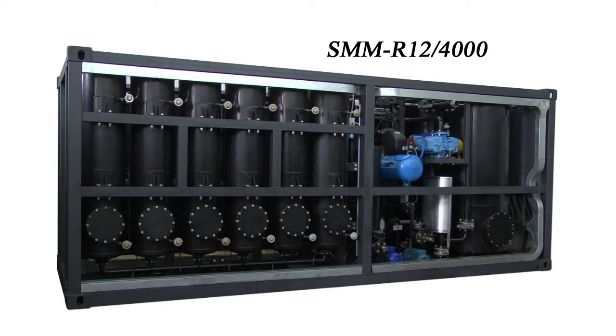When the reactivation cycle is complete, the system is again ready for oil regeneration. The sorbent in the system can be reactivated up to 300 times, which constitutes 1.5 to 2 years of operation, until it needs to be replaced. The replacement process is simple. The sorbent is reactivated one last time and is unloaded from the columns in dry state. Waste sorbent is environmentally inert. It can be disposed of as construction site waste or household waste.